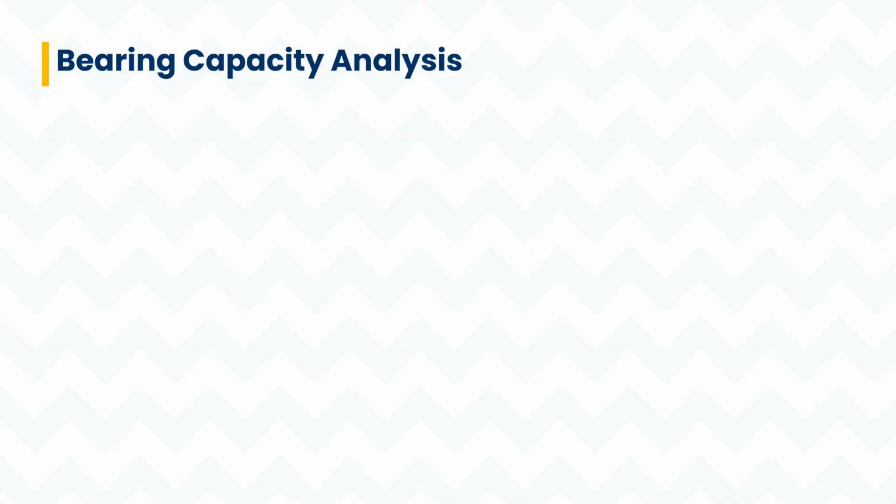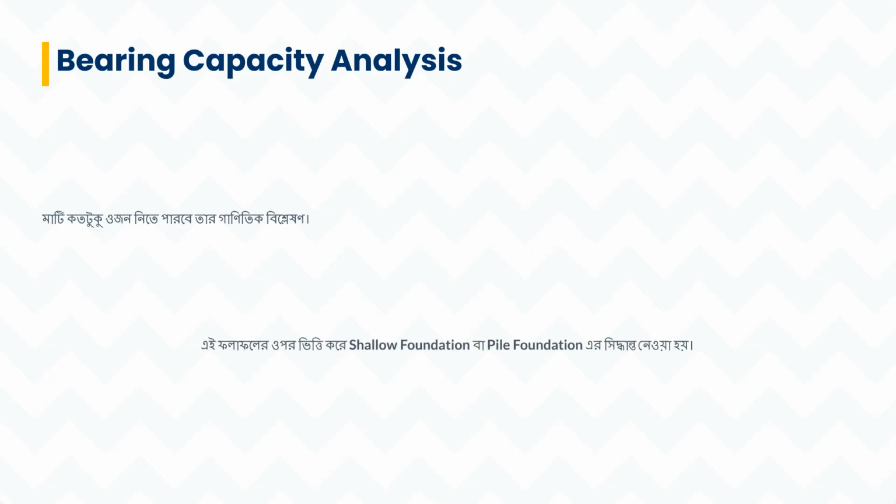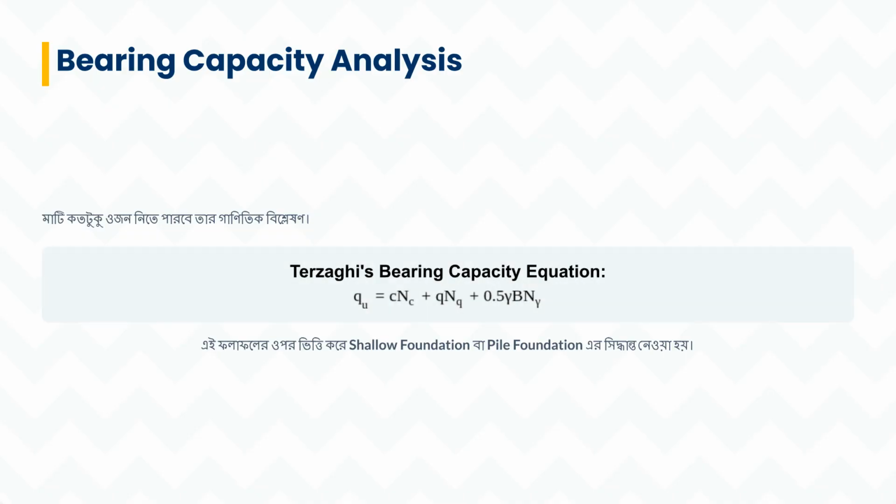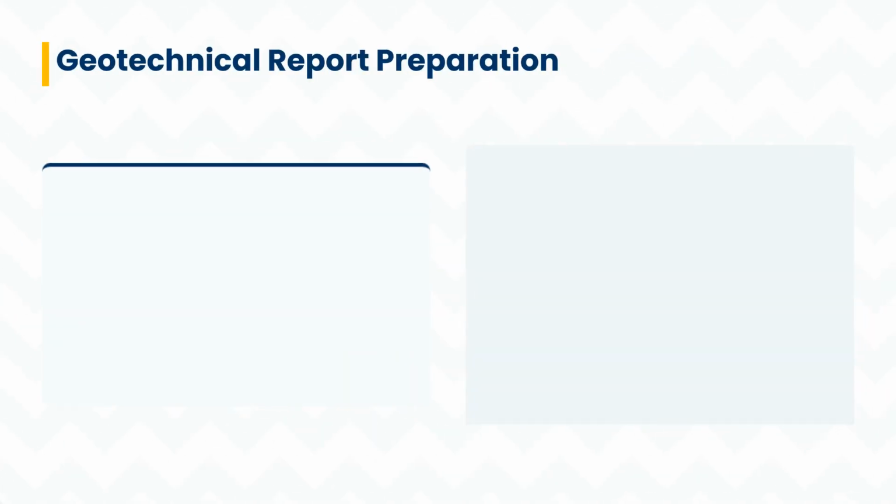Bearing capacity analysis involves mathematical analysis of how much weight the soil can support. The final decision on whether to use a shallow foundation or pile foundation is based on this result, often using Terzaghi's bearing capacity equation. The geotechnical report is the final documentation.